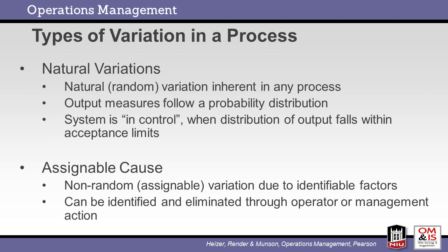Process variability has two causes, random and assignable. The goal of SPC is to reduce or eliminate assignable causes of variation. Some variability is inevitable. The goal is to ensure that product variability falls within acceptable limits. Some practitioners believe that the variability deemed to be random is simply assignable variation that is yet to be fully understood.